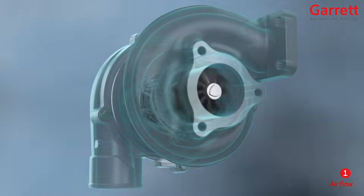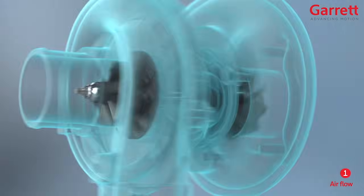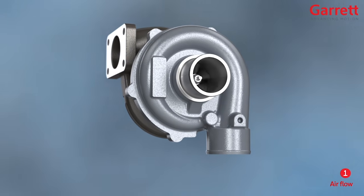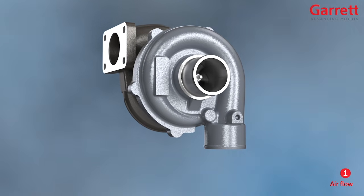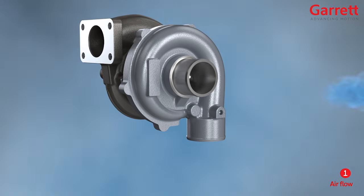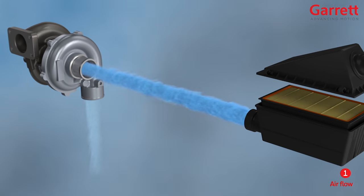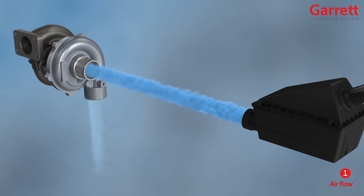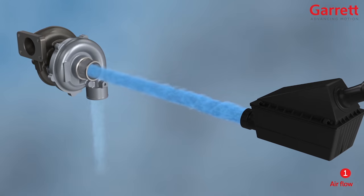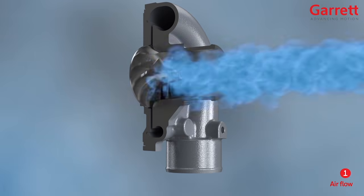On the other end of the turbine shaft, spinning at the same high speed, is the compressor wheel. For the engine to burn fuel more efficiently, it needs as much oxygen as possible. Compressing the air increases the density, so more oxygen per unit of volume. The spinning compressor wheel draws ambient air through the air filter, which is critical to the correct operation of the turbo, into the compressor inlet, where the air meets the compressor inducer or inlet blades. The air passes between the blades and is accelerated up to extremely high speed.